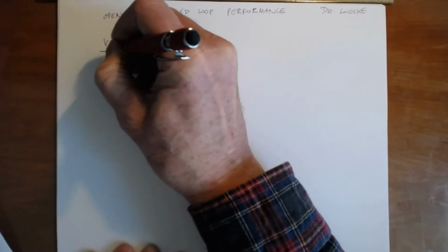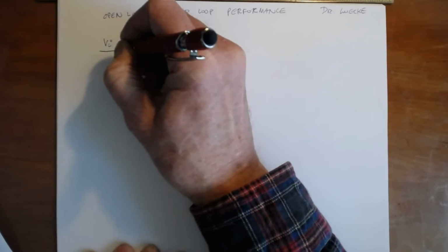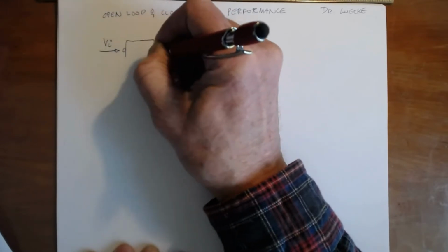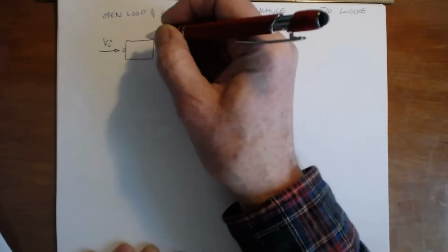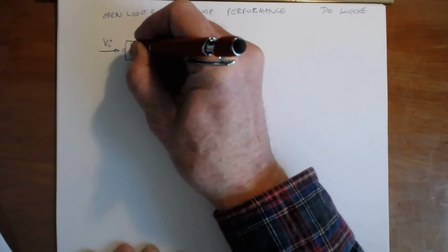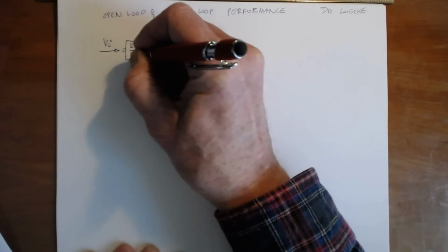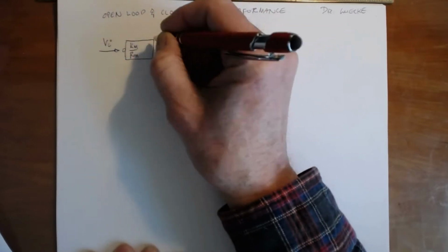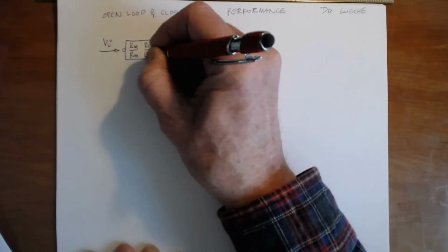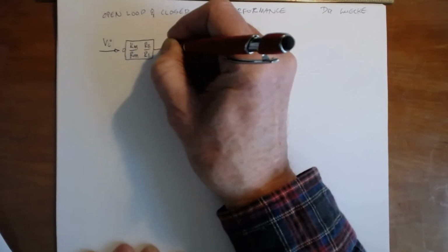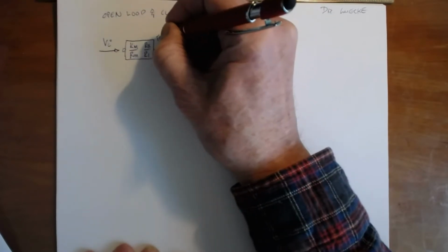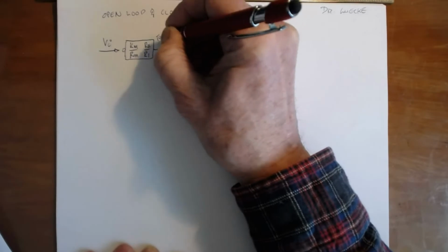We've got an input voltage that comes in. We went through the trouble to neglect the inductance on our motor, and so we have the motor torque constant Km. We have a resistance on the winding Rm. I've chosen to use the gear radii R2 over R1, and what this does is this puts out the torque from the motor.